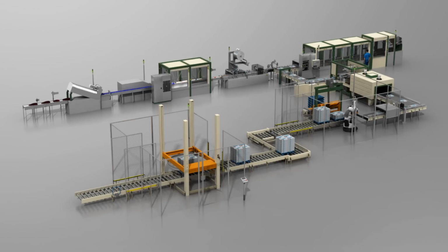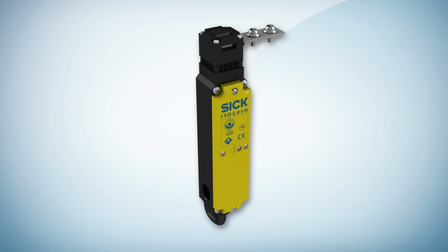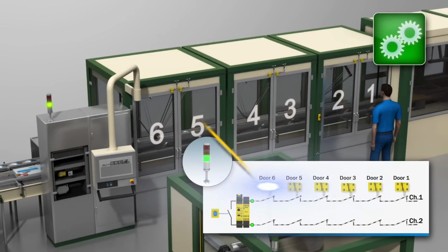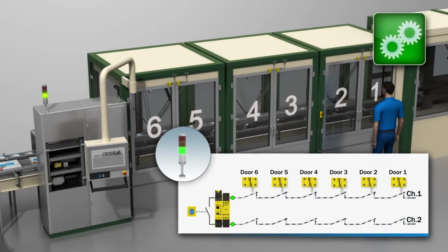Fault masking can occur in a series connection of switches with volt-free contacts, independent of their manufacturer. These include non-contact magnetic safety switches, electromechanical safety switches, and safety locking devices. To see how fault masking occurs, let's have a closer look at a packaging machine. The hazardous part of this machine is secured with 6 doors. Each door is being monitored by a magnetic safety switch.